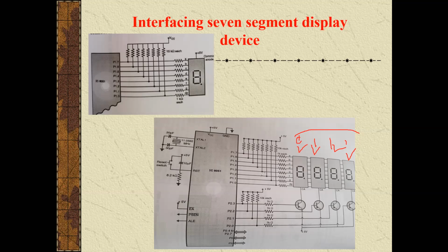So this is enough for the day. In this lecture, we have explained the theory about the push button, matrix keypad, non-matrix keypad, and the basics behind the 7-segment display. There are 2 types of LED configuration, common cathode and common anode. For our microcontroller purpose, common anode 7-segment displays will be used. For displaying 4 different digits, 4 7-segment displays will be connected.